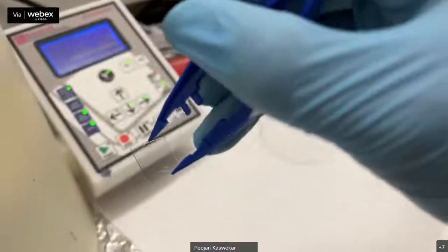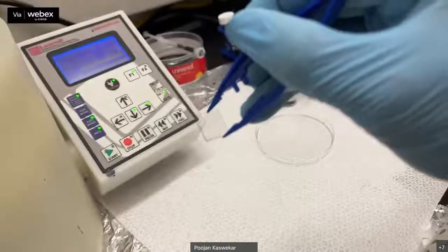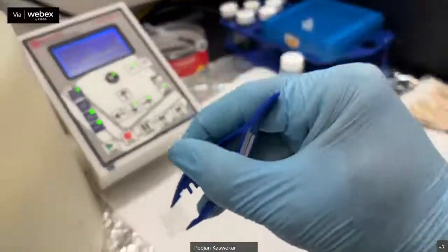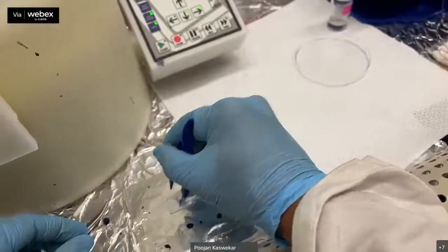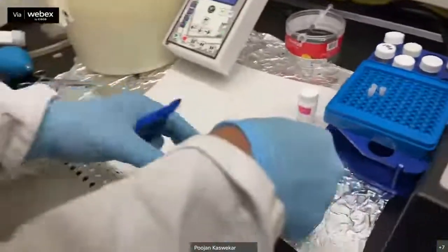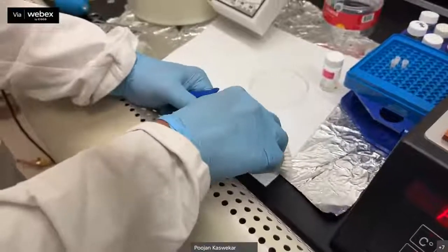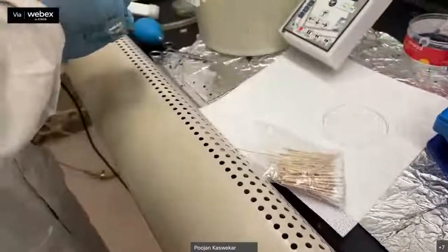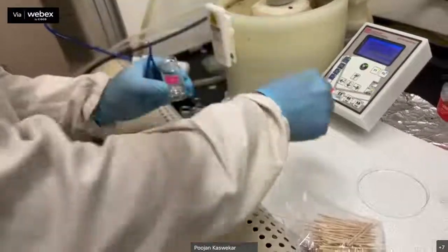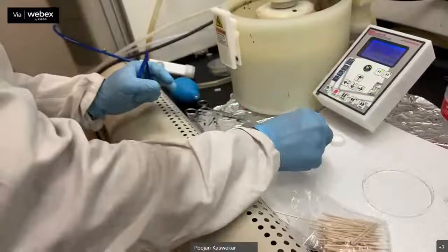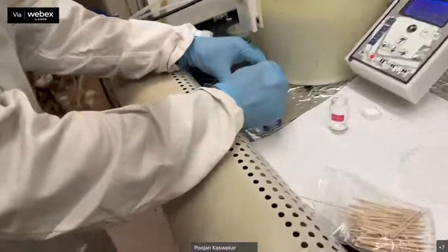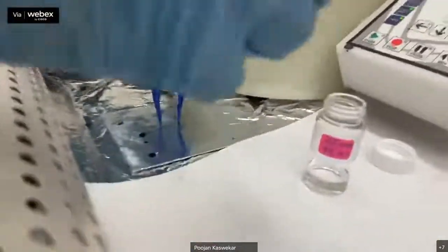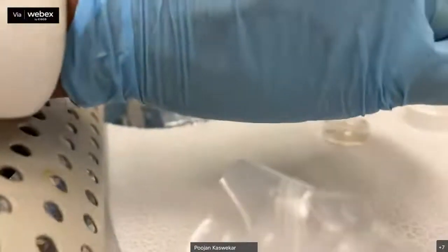You can see the spin coating quality is very good, since it's transparent without any particles and it's evenly coated. We use the cotton swab and dip it with the DI water for the etching. So we want to hold it with the pen to keep the sample stable.